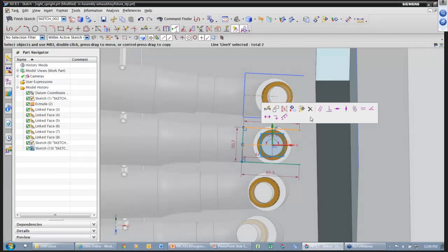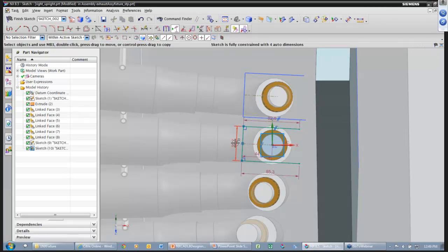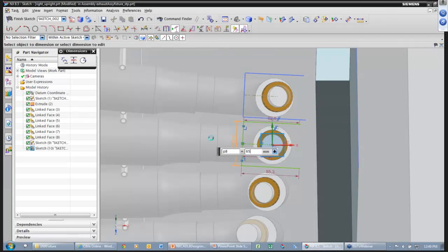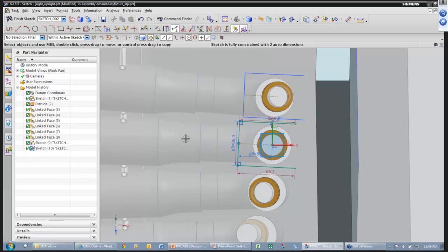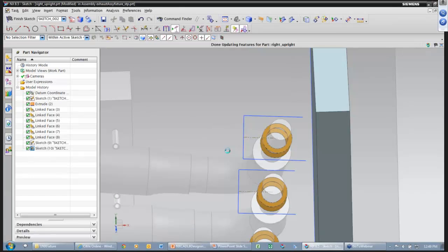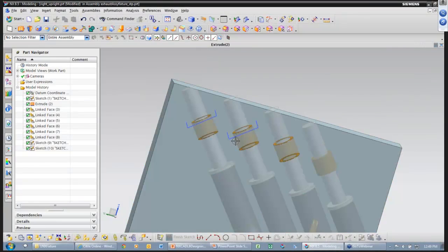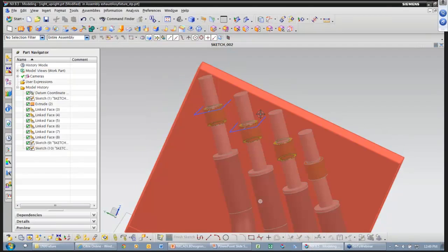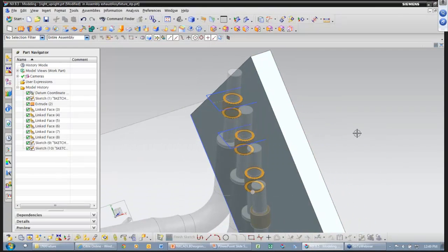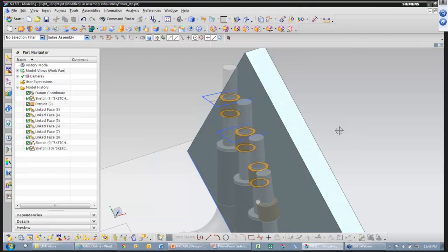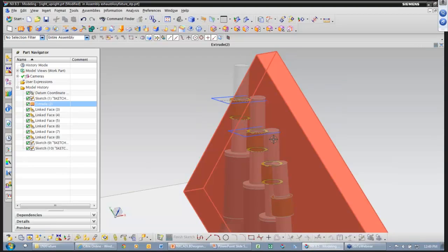And we'll build a couple constraints, make that parallel to get the right orientation there, and then we'll make that 65 as well and 50 from the center as we did before. So there's my other open profile. So notice they're at different orientations slightly, and they're also at different locations. I'm just referencing that copied face. Now the reason why I did the top and the bottom: the top will define the sketch and the top of that feature, and the bottom I'm going to extrude to.